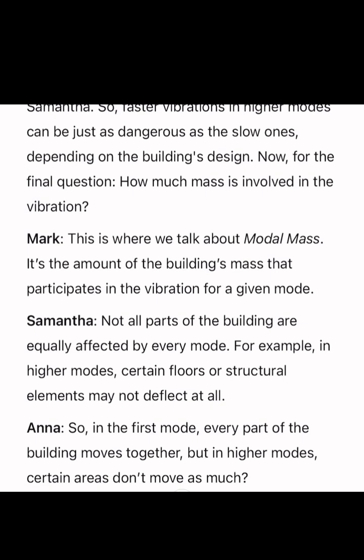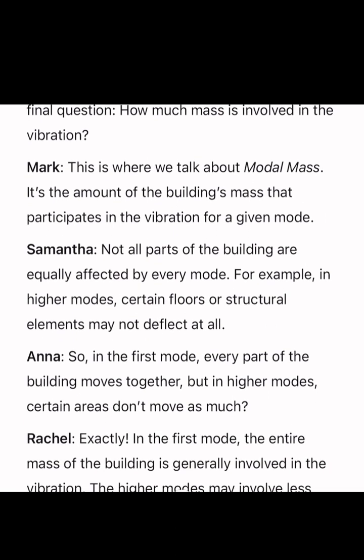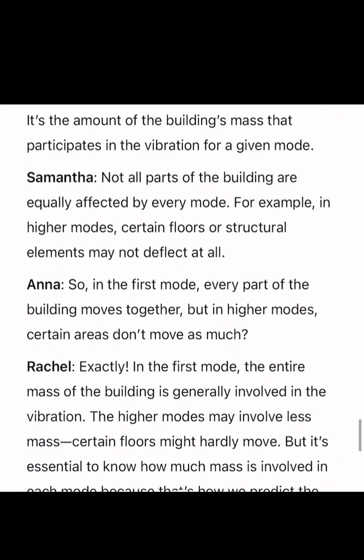This is where we talk about the modal mass. It's the amount of the building mass that participates in the vibration of a given mode. So for a particular mode, how much of the building mass is participating in that vibration? Not all parts of the building are equally affected by every mode. For example, in higher modes, certain floors or structural elements may not deflect at all.